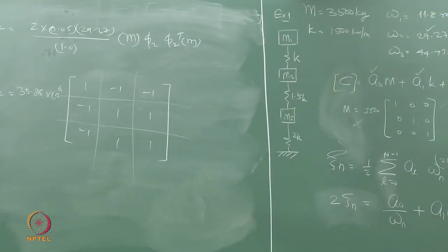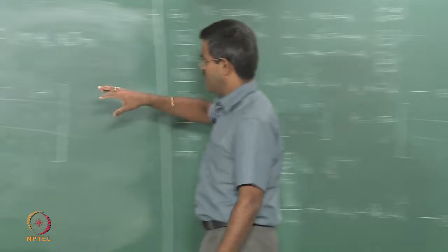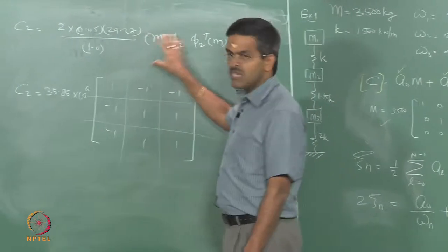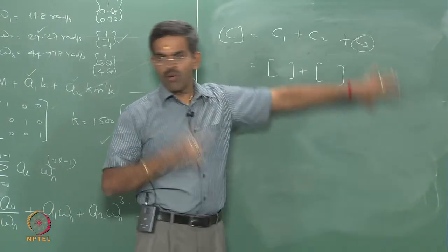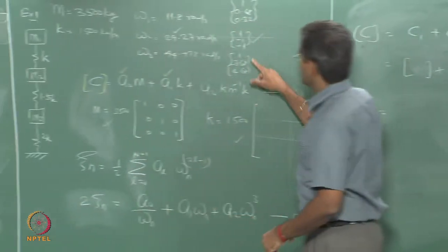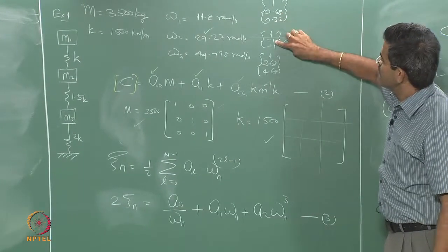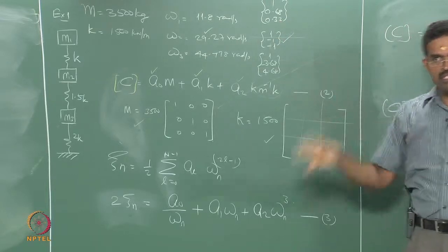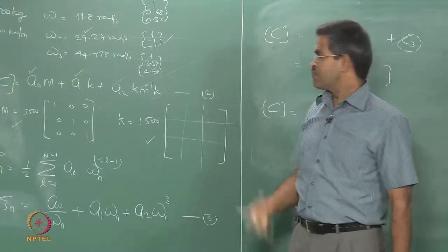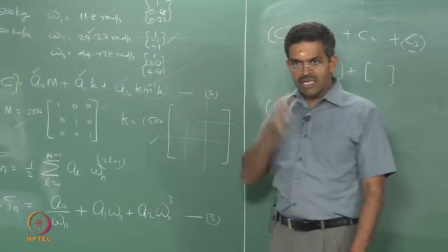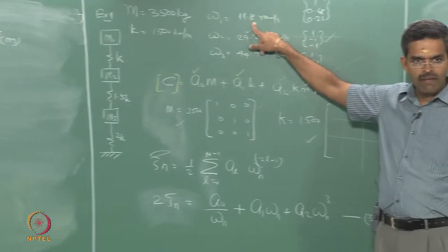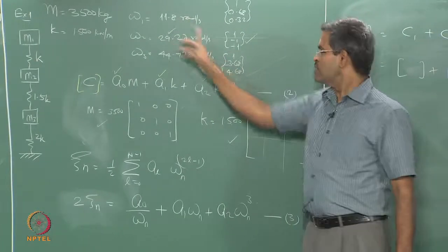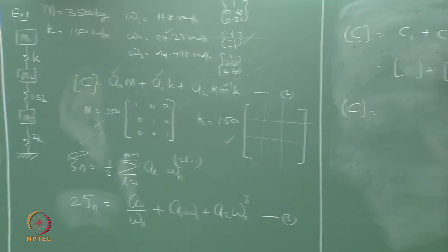Okay, mass and mode shapes are very important. Frequencies are also important in this case, but mode shapes are equally important, because they will tell you what is the effective contribution of that particular vibration mode in the overall damping, because they are compromising. Okay, one is positive, one becomes negative. So, they may compromise on each other in terms of the vibration mode. After all, modes are nothing but relative displacements of mass points at a given frequency of vibration. Okay. So, that is how I do not have an influence of C3 on C.